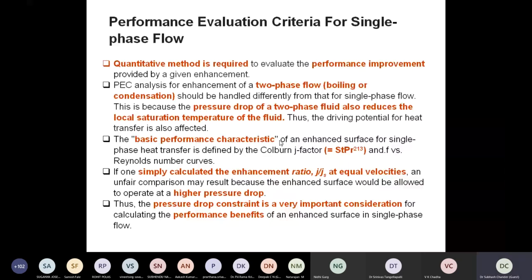On the one side we are getting a benefit, on the other side we are also getting penalized in the form of pressure drop. So if there is more pressure drop across that particular device, then we have to increase the size of the pump. That will again add to the cost, right? So that will not be advisable, we can say, as a recommendation, right?